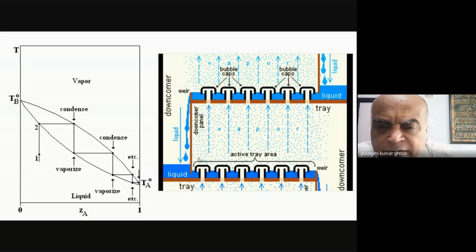So first we talked about compression. That is the work that I have to do and which effectively sets the stage for the subsequent liquefaction, a crude liquefaction into some vapor and some liquid. Then what I have to do is that I have to now more cleanly separate the oxygen and nitrogen, which is done through a standard fractional distillation, except that you're doing a very low temperature fractional distillation. Otherwise, it's the same thing. There's no difference between the two.